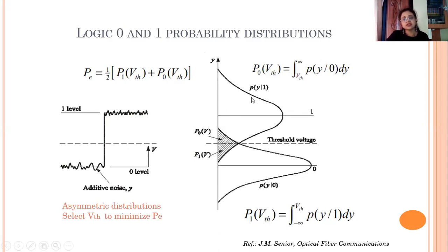Now, this particular probability density function, when bit 1 is transmitted, is actually somewhat like when there is light present. Recall in digital communication, I told you, when my input information signal is bit 1, at that time in the modulated output a light pulse is present, and if it is bit 0, the light source is switched off and no more light pulse is present.